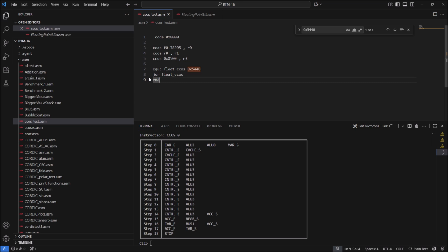So this is a preferred method because with this method we've got a way to generate the cosine of a function using the CORDIC unit for an entire range, the entire domain of inputs. So it won't just work between minus 90 degrees to plus 90 degrees, it will work over the entire range.